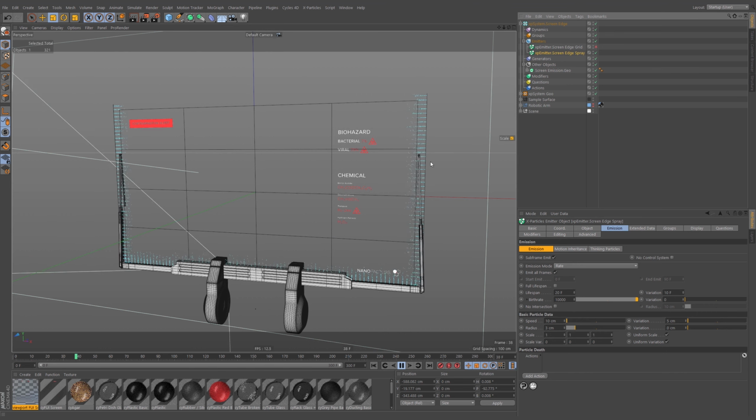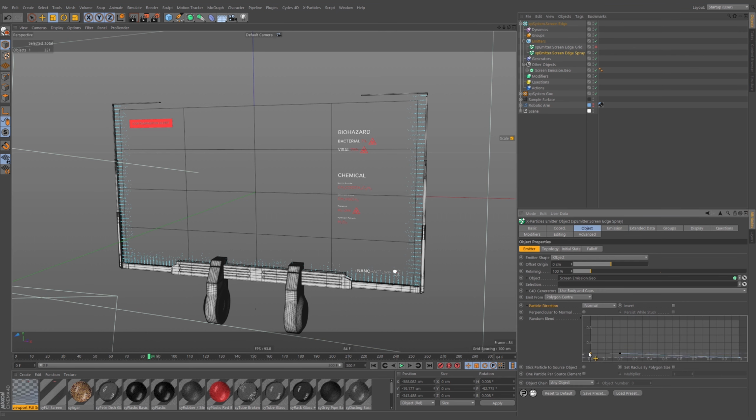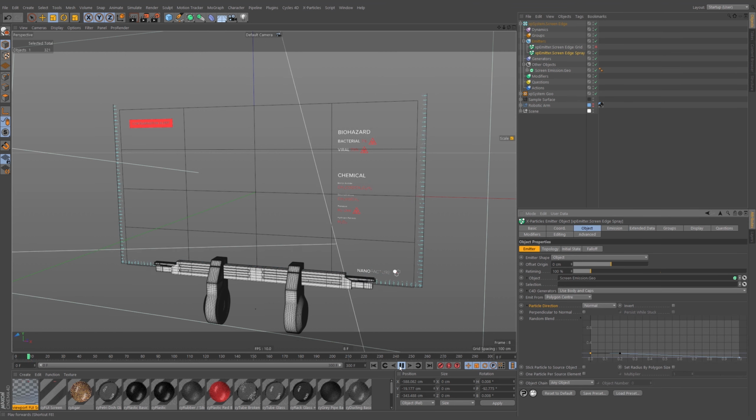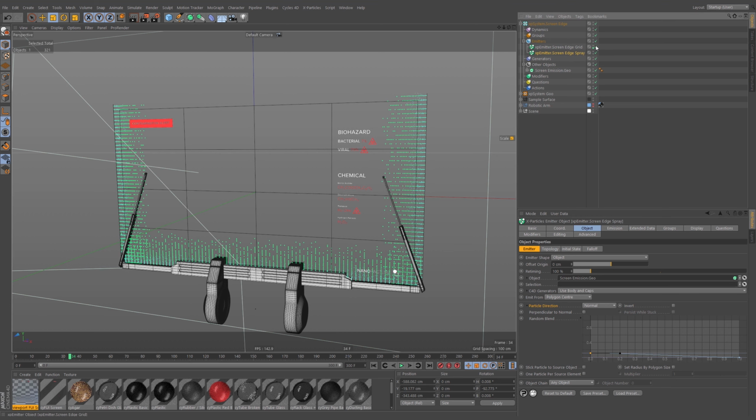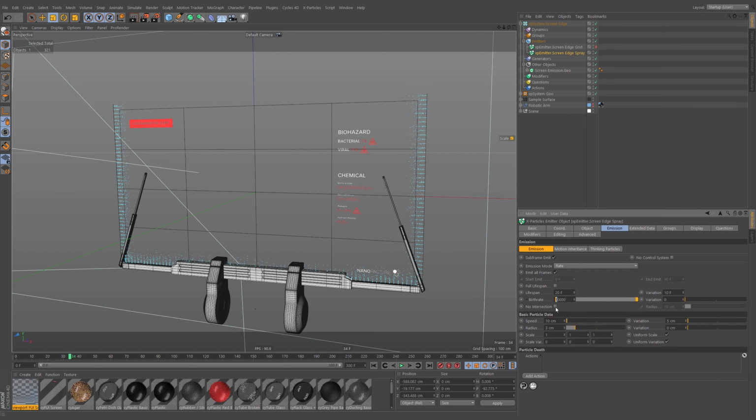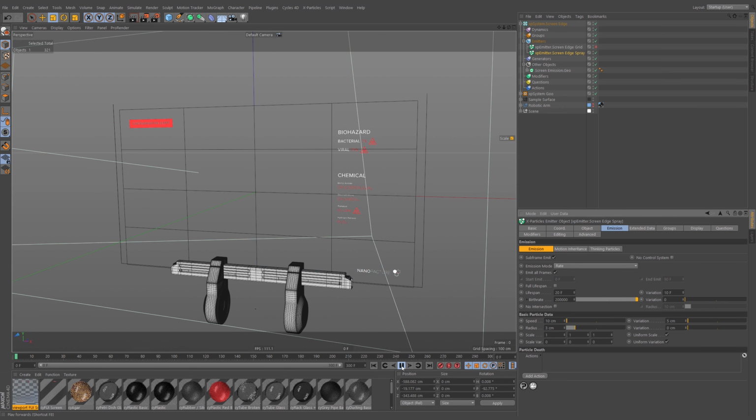That's pretty cool. So you can imagine these little nozzles here are spraying out this, whatever this is. I might have it a bit wider. Currently it's a bit bunched up. I think we'll definitely go denser for the final as well. Because you've got to remember, when we've got these ones on as well, I don't want these to be lost. I want them to be quite a significant element. So let's really crank this up. I'm going to go to 100,000 per second. Maybe I'm going to go 200,000 per second. That's a lot of particles, so we'll have to be a bit careful on time.